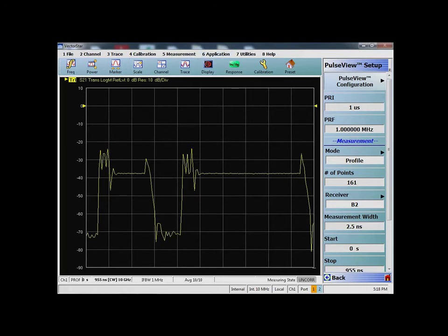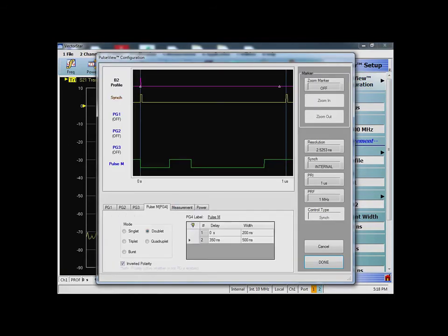So this was for the doublet. Just like that, you can also do a triplet. And now, because we will have 3 pulses, let me quickly do some changes. So first pulse I want to make 100 nanoseconds. The second one I can start with actually 200 nanoseconds and stop at maybe again 100 nanoseconds of pulse width, right? And the third one, because this is not 200, 300, so let's do 350 nanoseconds, and then we say, okay, even for this pulse I need 100 nanoseconds of pulse width.